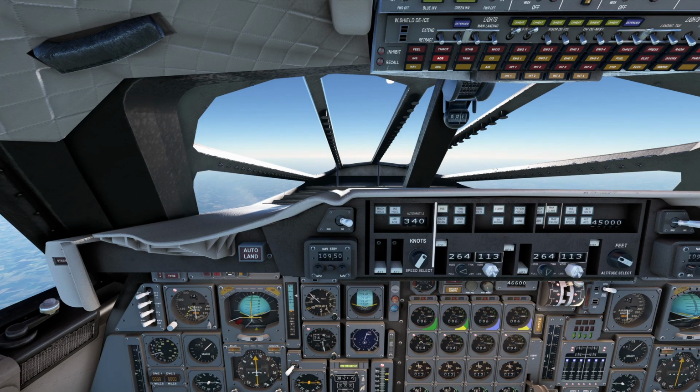The max climb mode is a lower ascent rate. You can see it here, it goes back. So it is a balance between gaining speed and gaining height. If you're getting too fast, for example, above 45,000 feet, you can always go to Alt Acquire, which keeps the speed but maximizes the gain in height.